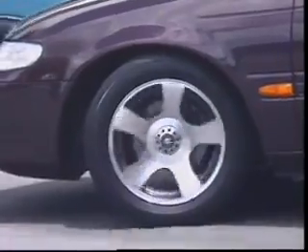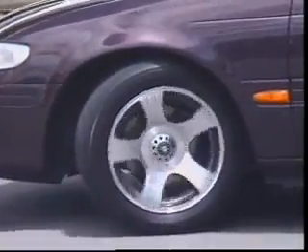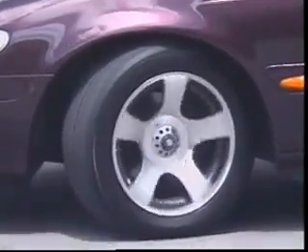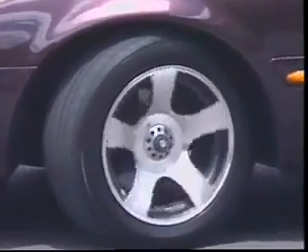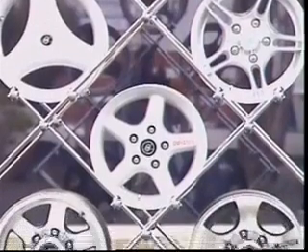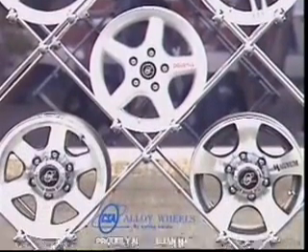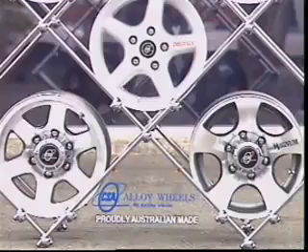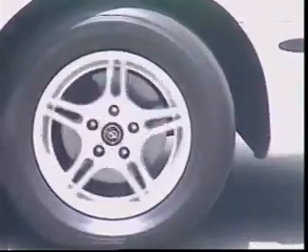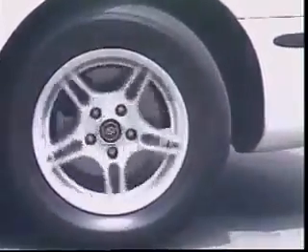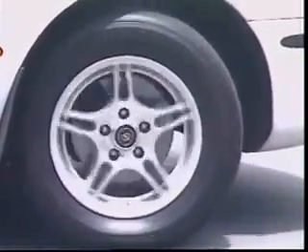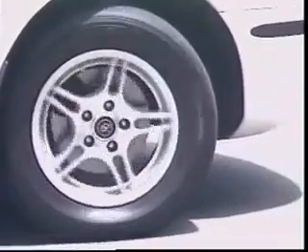Wheels can also be made from cast aluminium alloy. Alloy wheels are popular because of their appearance and because they are lighter than similar steel wheels. Aluminium is a better conductor of heat, so alloy wheels can dissipate heat from brakes and tires more effectively than steel ones. These are often called mag or magnesium wheels, but wheels made of magnesium are rarely used on road vehicles.